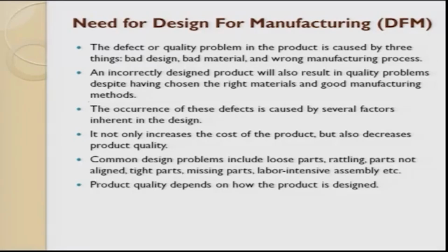So, here I do not waste material. The material which is put in as raw material itself, I get as output, and I exactly make 10. Through this process also you can make a polymer rod. If you see these two processes, in both the final outcome is achieved. But in the first process a lot of scrap is generated, and that is not accepted today in sustainable manufacturing.